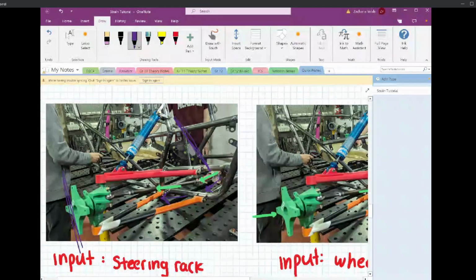Imagine your wheel is fixed, because instantaneously, when the driver puts any sort of load into the steering wheel, the wheel itself on the ground is going to try and resist that load by inertia, by friction, just by being there, as long as you're actually on the ground. So then you're going to see a force in the tie rod, which will be equivalent to the force the driver is putting in by inputting a torque onto the steering wheel. So that's one way you can get steering effort, almost.